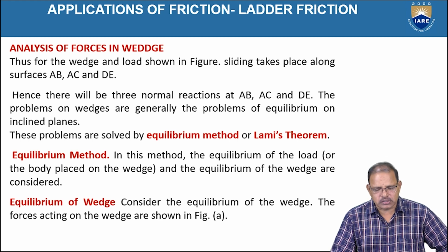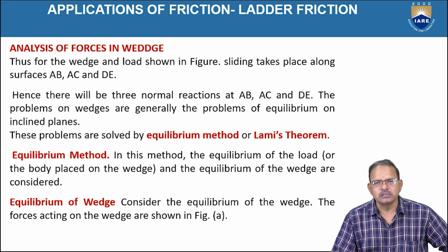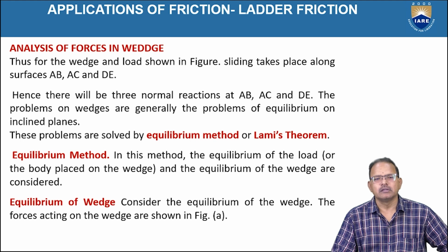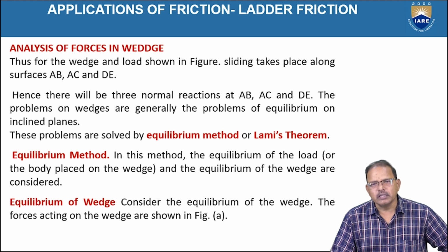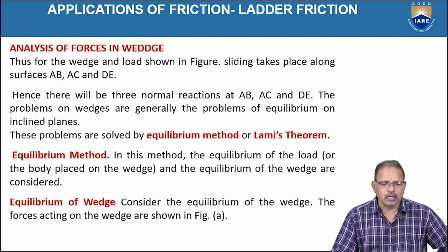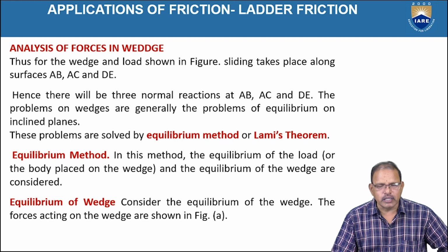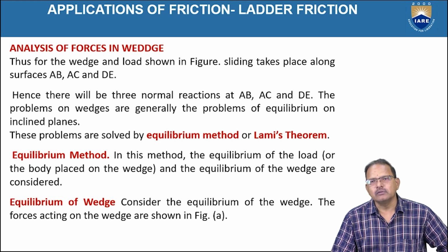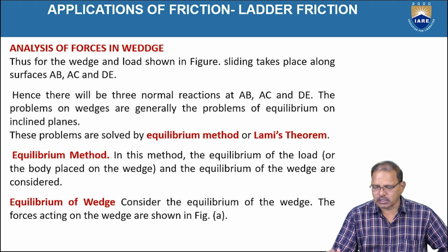The second method, Lami's method, is also applicable now. According to Lami's method, when three forces are acting simultaneously on a body in the equilibrium position, each force is always proportional to the sine of the angle between the other two forces. Already we have taken P, Q, R as the forces acting simultaneously.